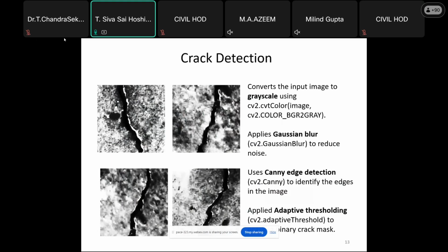It shows that these images have undergone image processing techniques such as grayscale. The crack detection depends completely on the contrast. This grayscale removes the color. Here you can see the function cv2.cvtColor with COLOR_BGR2GRAY. This function is used to convert the color image to the grayscale image.